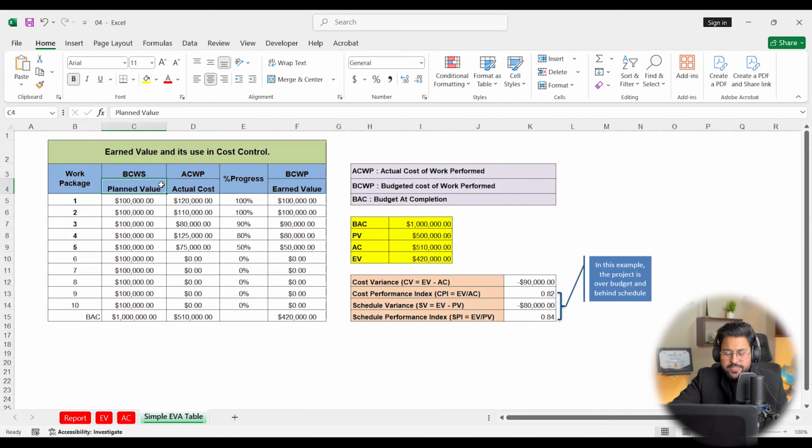These are the templates. Within Primavera P6, you can also switch. I will be showing you that one as well. But here you can see that on the basis of data collection from the site area, you are going to develop your progress reports and calculate all of these things. There are very simple formulas, but here you can see this is earned value. This is the simple template, but in Primavera P6, you can develop it as an automatic report, and it is going to show you how this is earned value management.